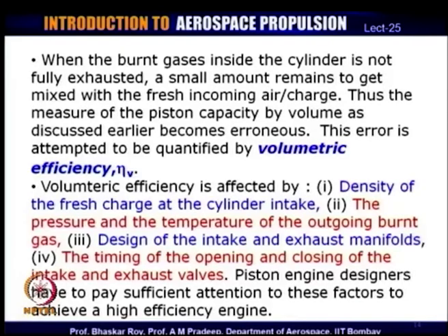Now, volumetric efficiency we shall define in a minute, but let us quickly understand what it is all about. What happens is the density of the fresh charge affects the volumetric efficiency, and we have seen in aircraft engines we need to raise this density through the process of supercharging, and then the pressure and the temperature of the atmosphere, the temperature of the outgoing burned gas which has remained or the residual amount, and then of course, how quickly or how efficiently the intake and the exhaust valves or manifolds as they are often called open and close.